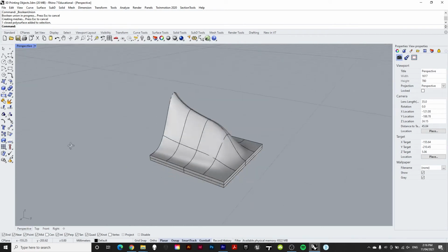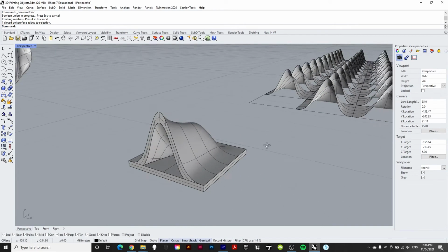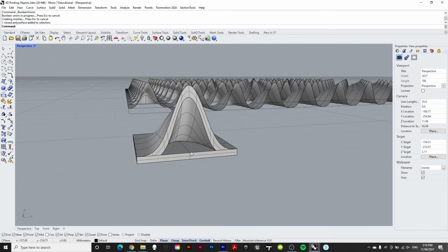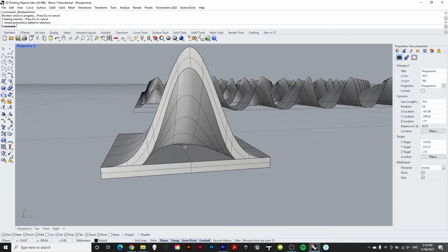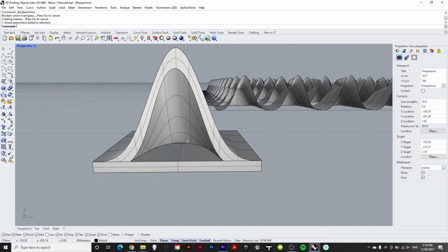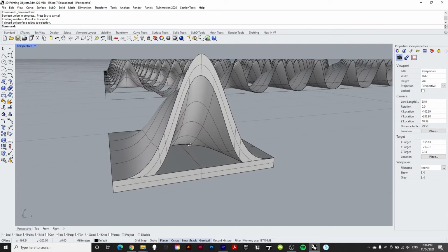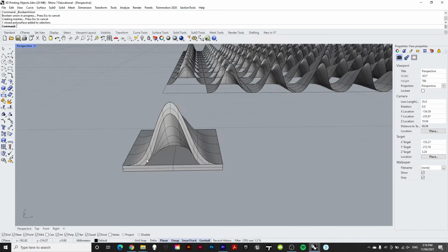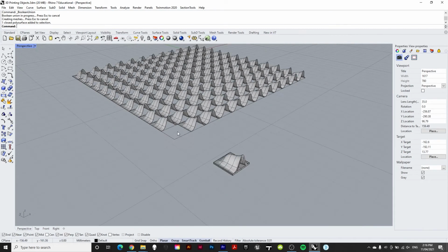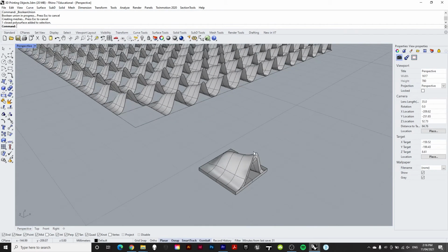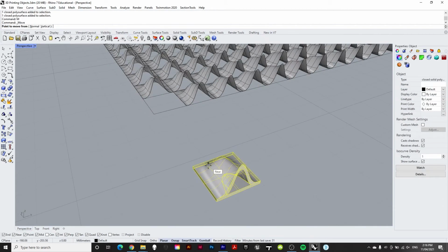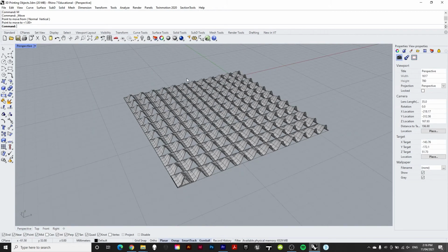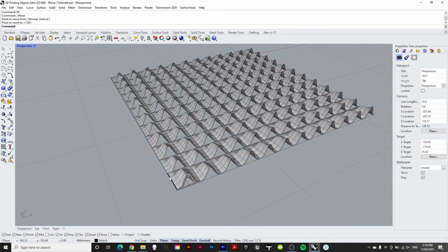And so we can see we've kept our original outside geometry. We've made our geometry a little bit easier to 3D print, less likely to fail. And also, if we do have to add any structural strength inside there with any supports, it's going to be much easier to get them out of this shallower hole that we have here than it would have been inside this big deep cavity out the back of there as well. So we would then move this back into position and then follow our array tool again. Delete all of these first, of course, and then follow with an array.